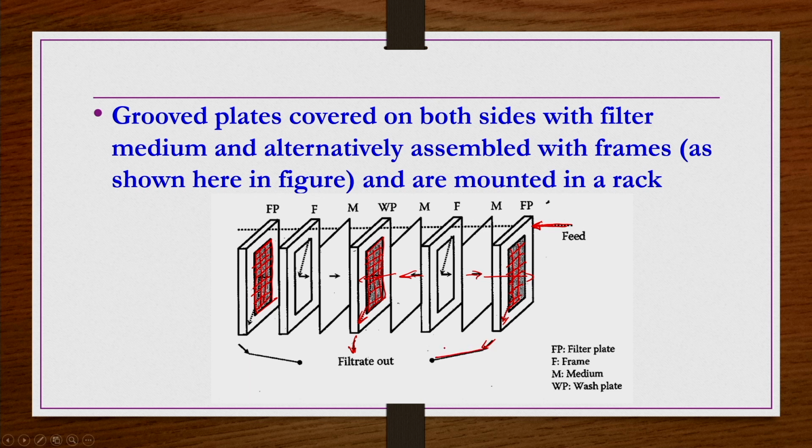Okay. So, here also, in the second set, the material is coming into the frame here. The material will be pushed towards either side of this frame, where we now have the filter plate and the wash plate. Those plates have filter cloths, so the filtrate liquid comes out through the filter cloth and is collected like this, right. Whatever solids are there will be deposited in the hollow center portion of the press. So, this is how it is a stack.